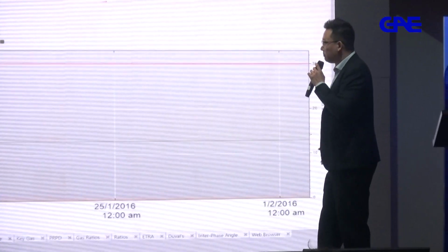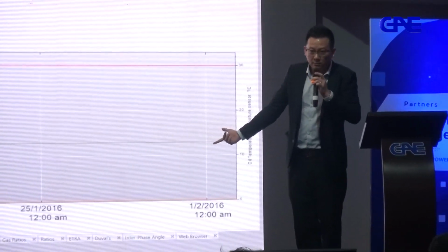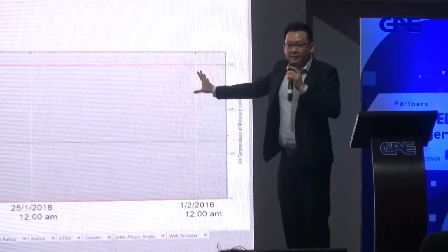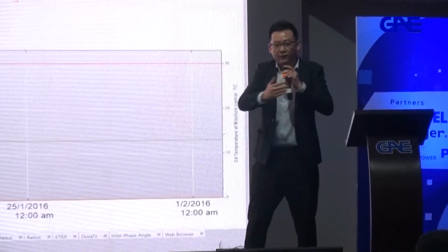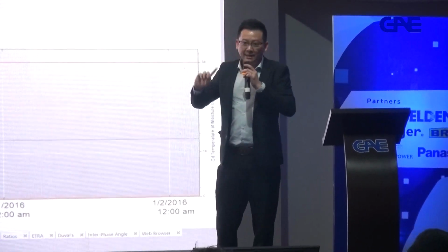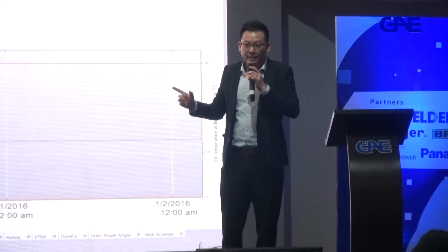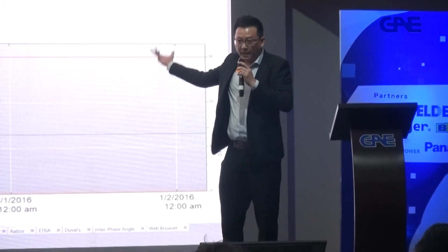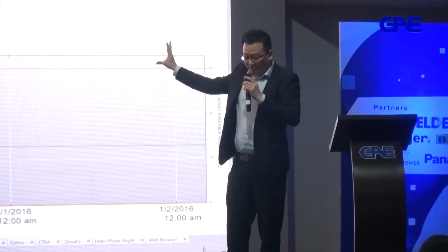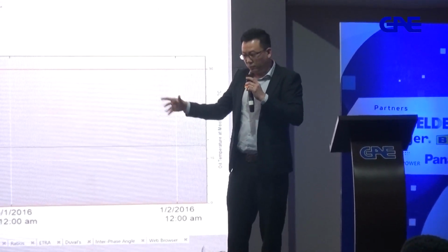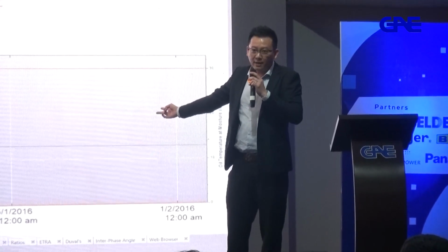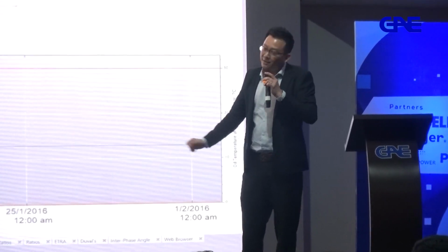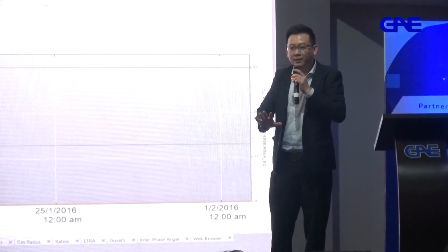If you look at the diverter and selector, the ppm will be a different value compared to the main tank, totally different, because there is a lot of tap changing going on inside. Especially in oil fields, you have to jack up the ppm. At the tank with the OLTC, 25,000 ppm of carbon dioxide and 5,000 ppm of carbon monoxide is normal, it's healthy.